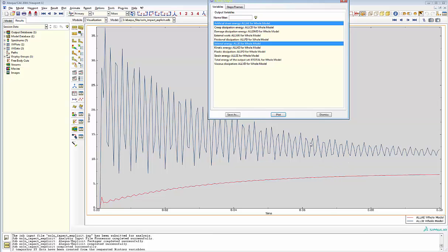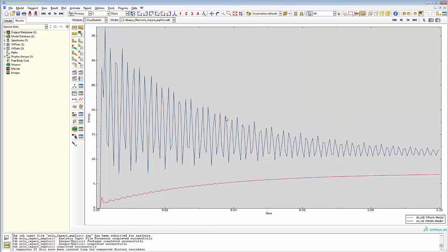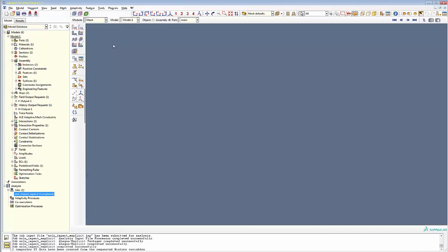That should give you a warning that indeed your model has some hourglassing situation or spurious shear or stiffness associated with the shear, meaning that the reduced integration formulation is not behaving properly. So my suggestion is that at this point, dismiss that. Don't even bother looking at the stress or strain data. And this is a clue for you to go back and change the mesh again.